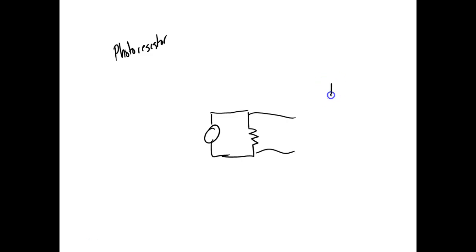So normally what we do is we'll come over here and put a fixed resistor in series with it, and we can swap this around, guys. So the sensor might be up here. It depends on how you want things to move. Now, if I take my output right here, then on this one, if the resistance of the sensor goes down, the output voltage would go down. If the resistance of the sensor goes up, the output voltage would go up, right? Y'all understand that?